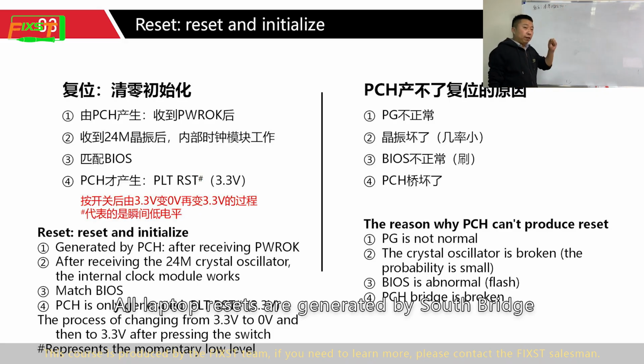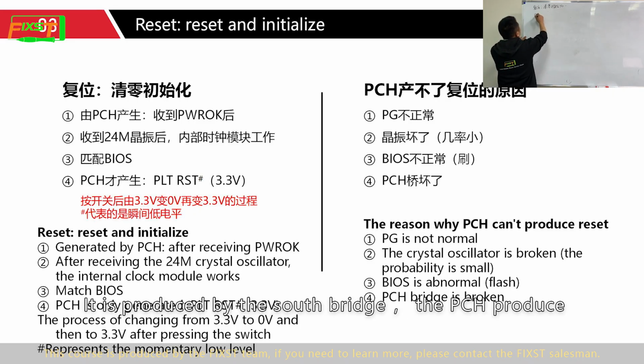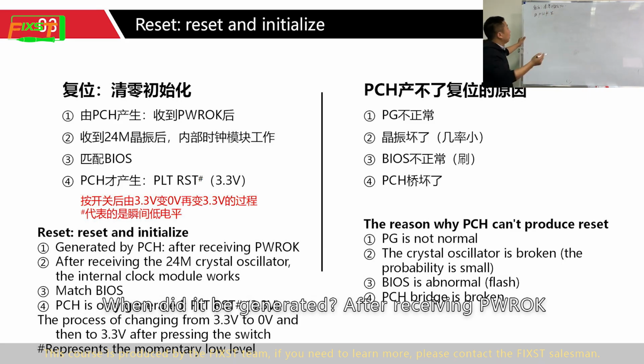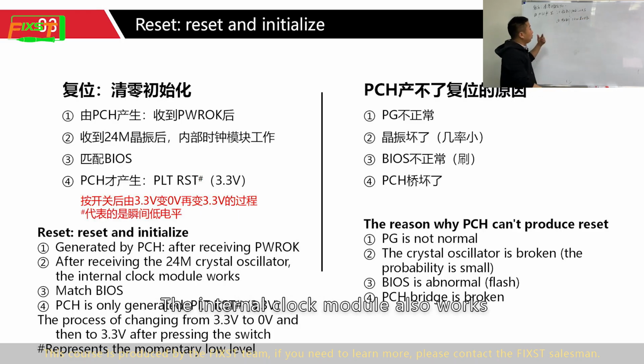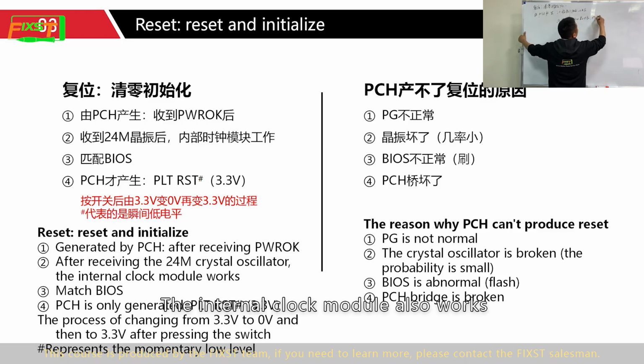All laptop resets are generated by the Southbridge. It is produced by the Southbridge, the PCH. When is it generated? After receiving power OK, and after receiving the 24 MHz crystal oscillator. The internal clock module also works.